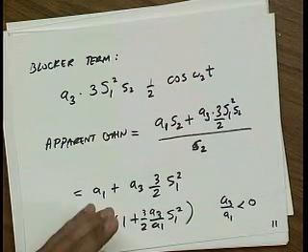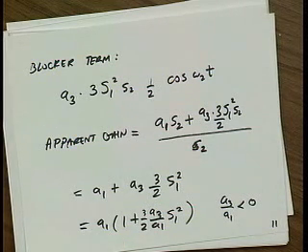Now, of course, you can always filter, right? And that's the solution that people use. You put lots of filters at the input of your amplifier to try to filter out as much as possible of the jammers. But a filter can only do so much, right? A filter maybe gives you 20 dB of attenuation. Well, someone can turn up their power by 20 dB. Filters are also very bulky and expensive. So if we can eliminate filters by making our amplifier more linear, that's always a win.